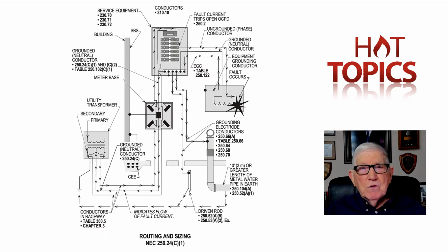In accordance with 250.118, the metal, if installed properly, all couplings tightened, connectors, threaded couplings, whatever it may be, then it can serve. But most engineers that I talk to today and do work with, they pull an equipment ground and everything. They say, if we start getting corrosion, loose connections, or whatever, we'll have two paths. We'll have the metal raceway path, if that's what we're using, and the equipment ground.